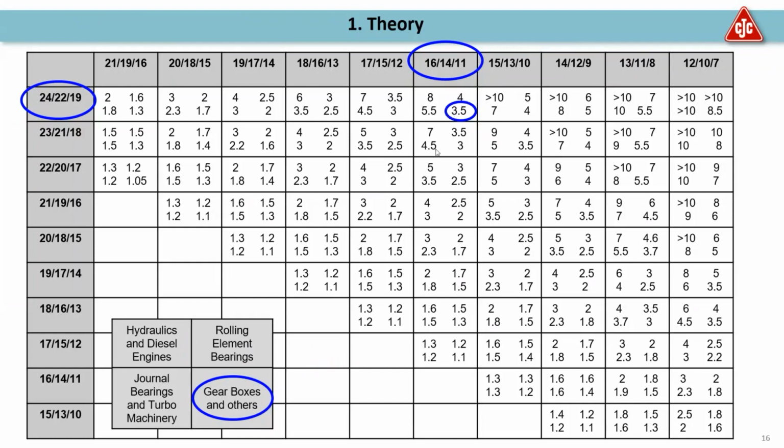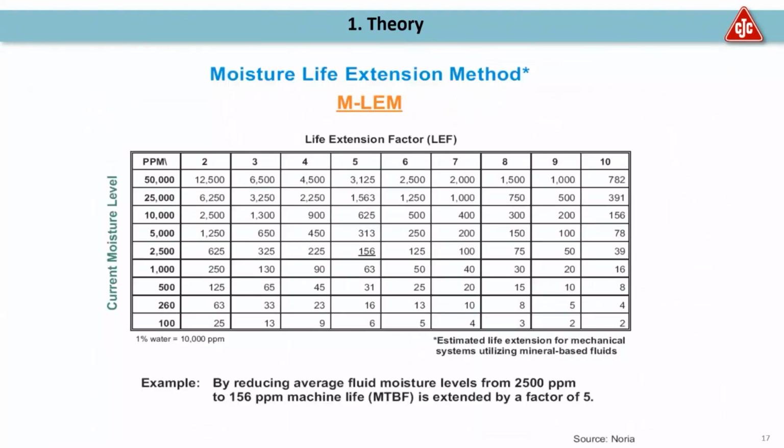And I say that because in most cases that we have looked at with gearboxes, first goes the bearing, there is more room for gears to grind. The gears start to grind, and then the gears go. So you can make an argument that the roller bearing is the most important one.